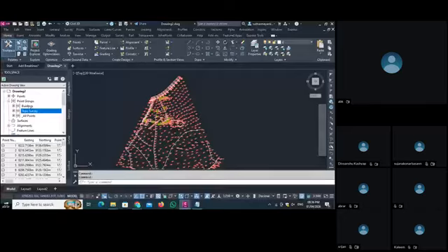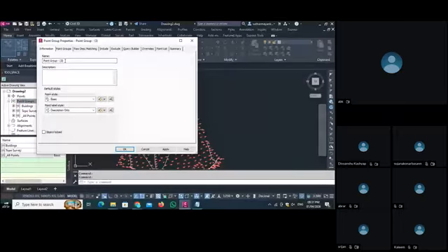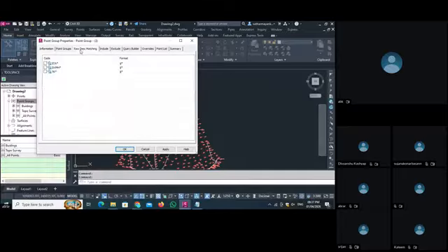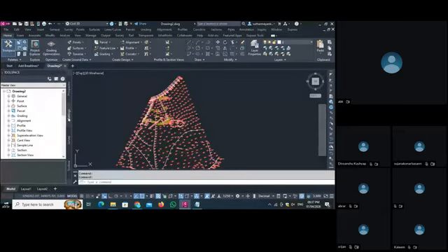We first create a point group as Building. Now if we again go to this new point group, the second method is, in the raw description matching, we have only these 3 groups. So what we do, we go here in Settings, go here to Point, then Description Key Set is here. Click on this plus icon, then the Civil 3D named description key is there.